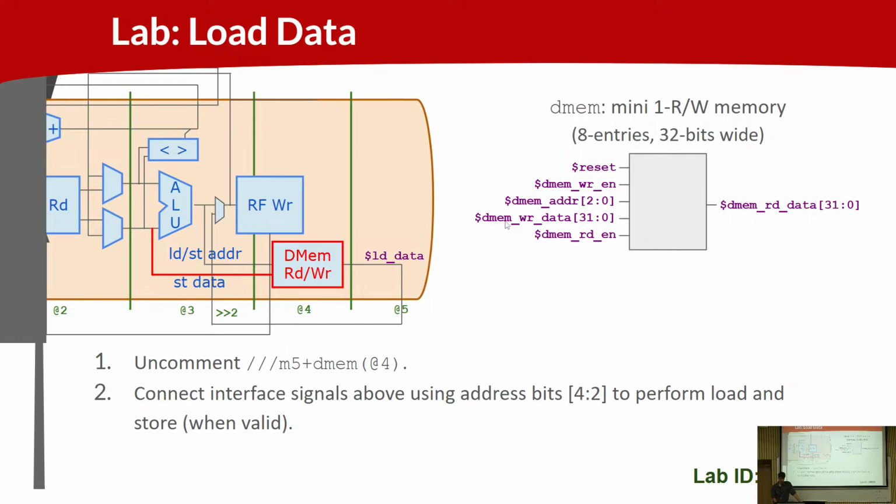And the write enable and the write data, and then on the read side we're using the same address input and a read enable. And for reads or loads, same thing, we have data coming back. So we have read data, which becomes our load data. So hooking this up and giving the signals names that make sense in the context of a CPU.